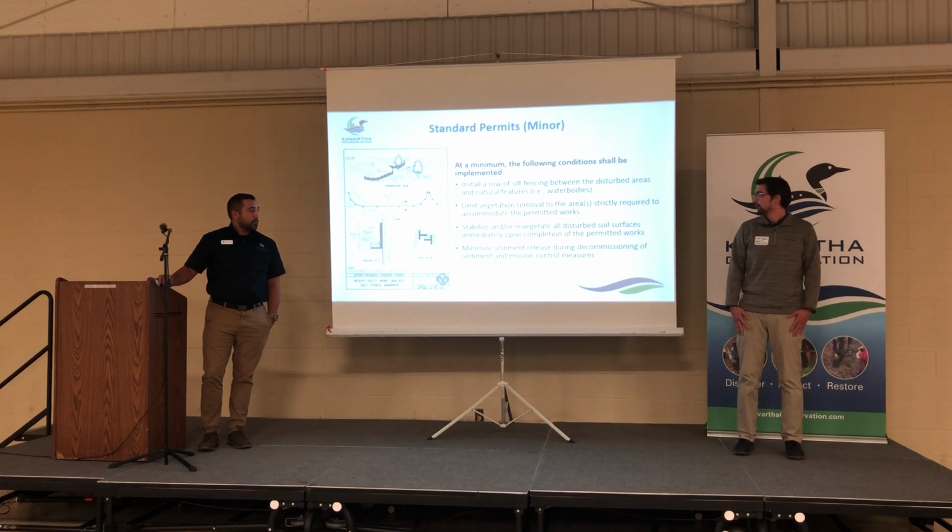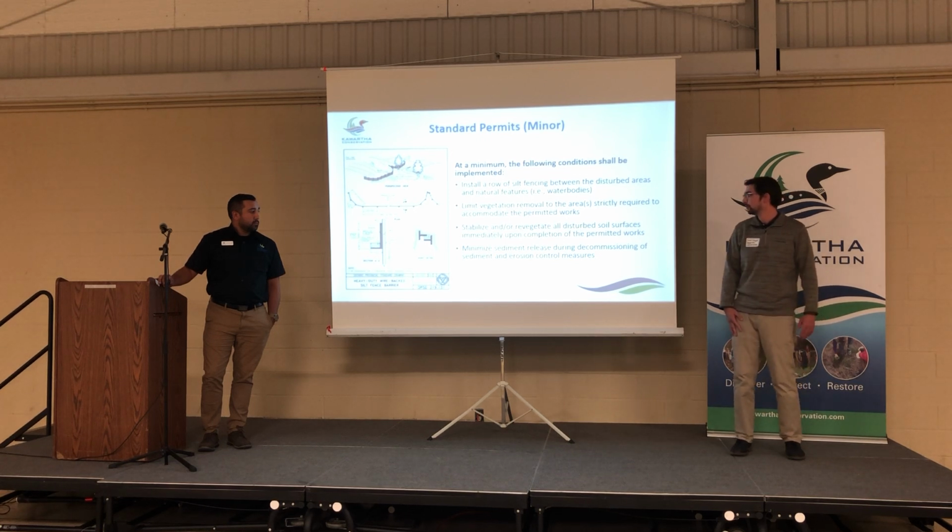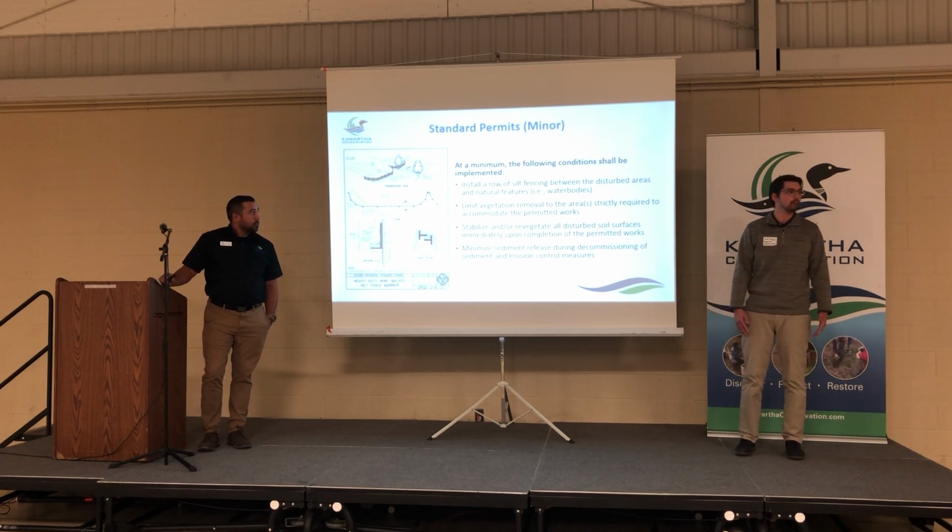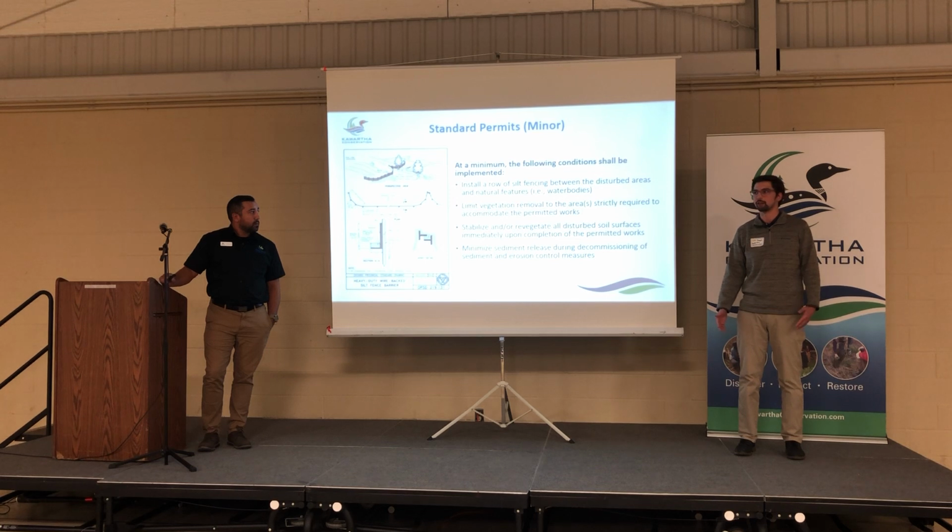Stabilize or revegetate all disturbed soil surfaces immediately upon completion of the permitted works, and minimize sediment release during decommissioning of sediment and erosion control measures. And in general, we would request that no sediment be allowed to leave the property, or in the case of larger development applications, the overall work site.